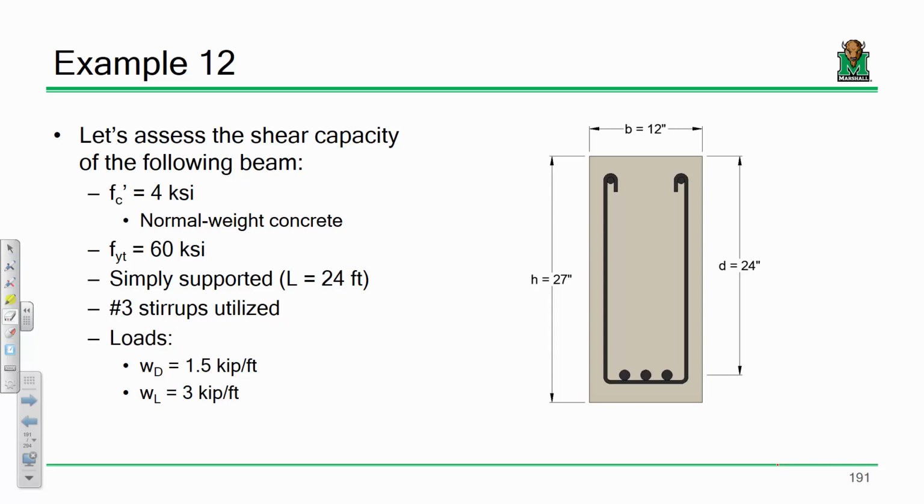One of the things about shear design, and I didn't really go into this earlier, but I should mention it while you're writing this down: shear design is always a known cross-section design problem. Shear design is always done after you've done moment design. So you've already figured out the shape of the beam and the reinforcement in the beam, whether it's a T-beam or rectangle or whatever. Then you come back and do shear. I don't want to say it's an afterthought, but you do that after you've figured out everything else.